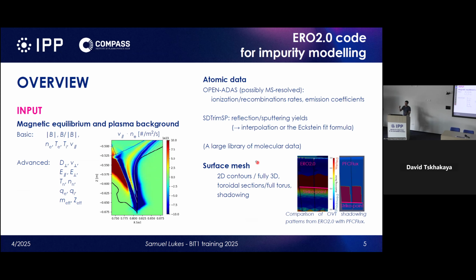So the mesh of the surface doesn't actually affect the sheath anyhow. The sheath itself in the normal direction is not resolved at all. It's assumed only analytically. You know the position of the particle, how far it is from the surface, and therefore you can immediately calculate for this one particle what the sheath effect is. Okay, I see. Cool. Thanks.